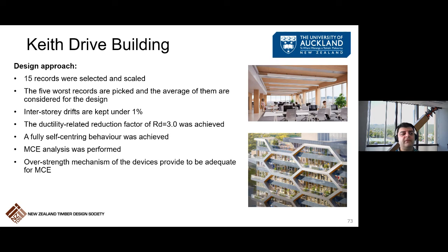For the ones who are curious how they do time history in Canada, they pick 15 records, and then they run the analysis. They identify the 5 worst ones and then average them. Here we mostly use a max of 3, so there's a difference here.